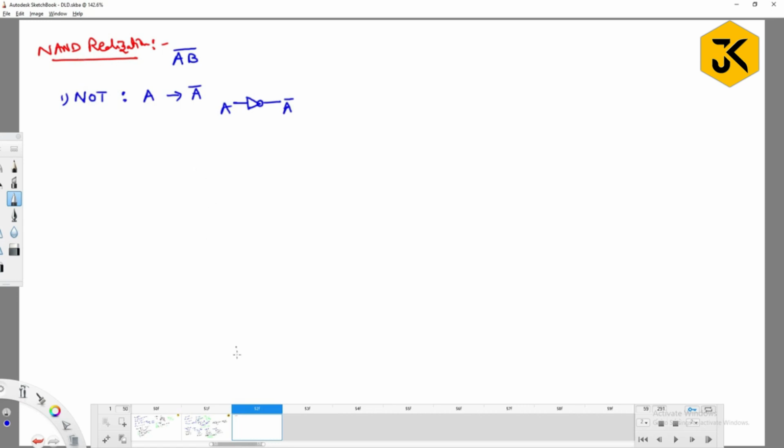Yes. Right. I think while discussing in the previous class itself, I have shown this one. See, if you are going to have the NOT gate, try to observe. If you are going to have a NAND gate, it looks like this. So the NAND gate symbol is like this only, right? Try to give two inputs as A and A. What is A and A? A, that will be complemented to A complement only, meaning that it will act as a NOT gate, right?